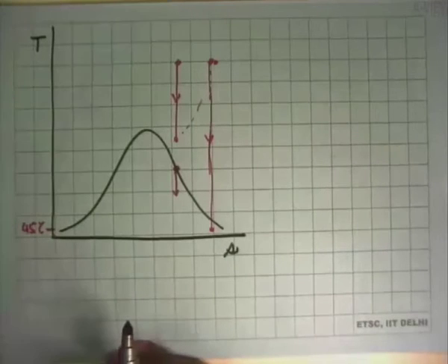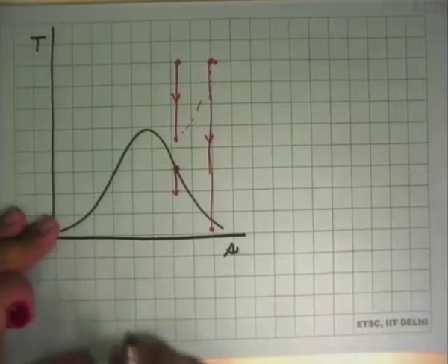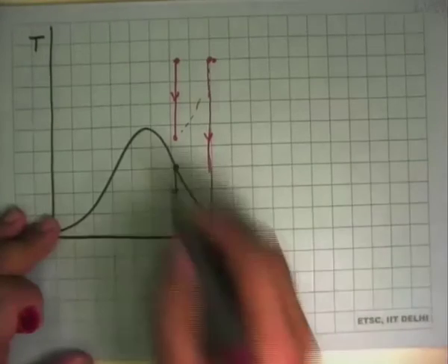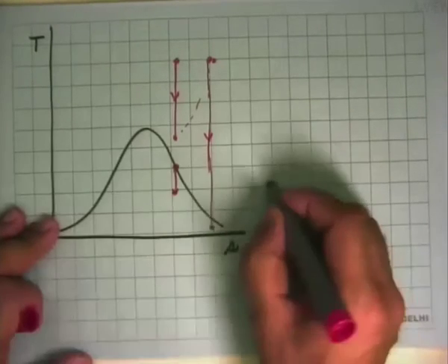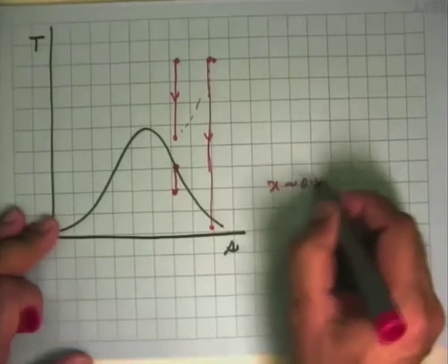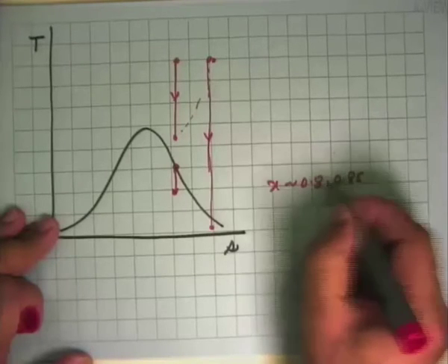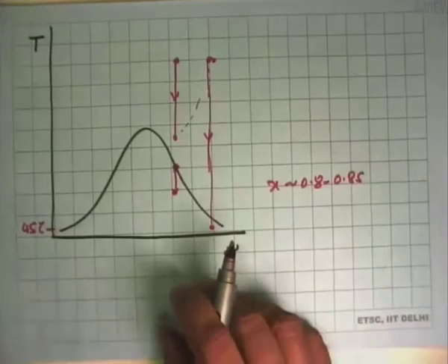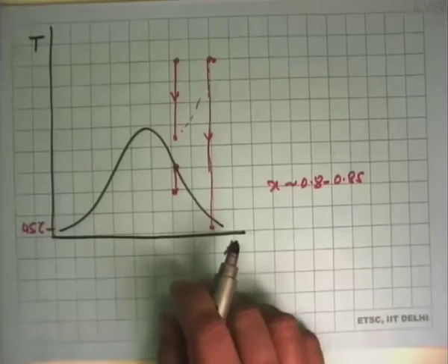And as you keep expanding, the quality keeps going down, so the engineering keeps getting complicated. So we say that, okay, I will come to a point where X is of the order of, say, 0.8 or 0.85, and then I cannot tolerate too much liquid in the turbine. It will break my turbine.